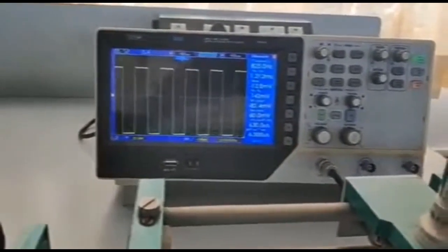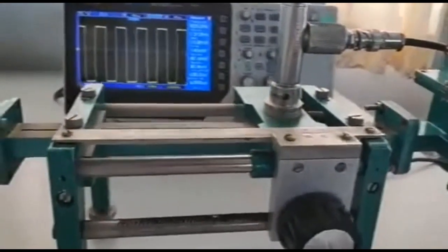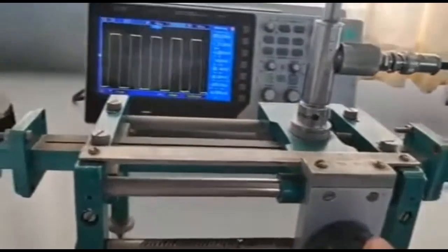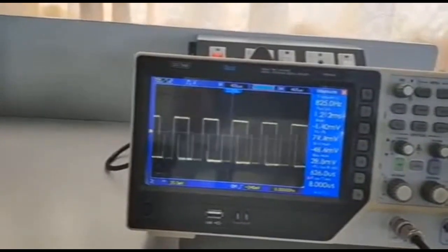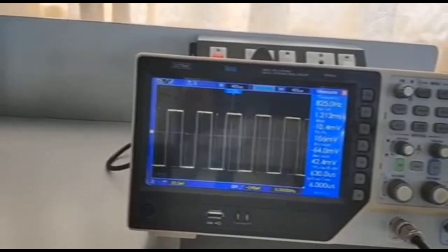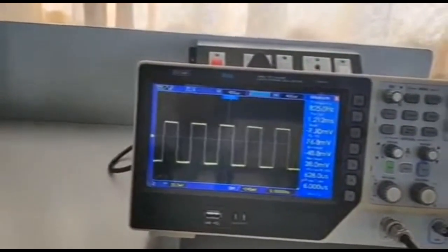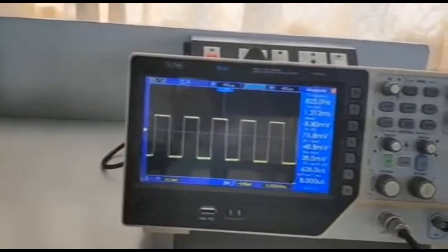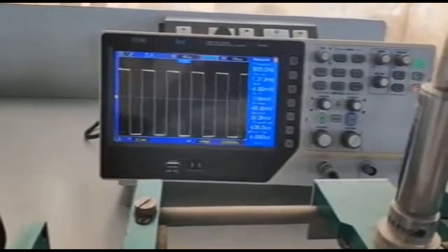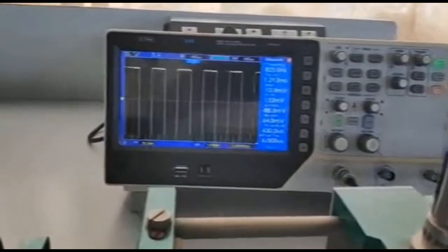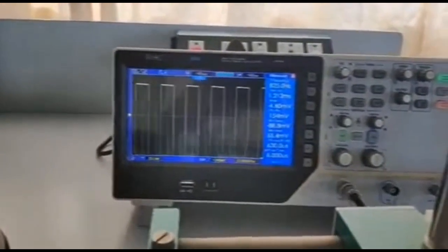In order to find the VSWR, I need to measure the minimum voltage and the maximum voltage. So to measure that, rotate this SLC knob and observe the voltage. So the voltage is getting reduced. So this is the minimum voltage, 76.8 millivolt. Similarly, continue this rotation in order to obtain the maximum voltage. Okay, so I got 153, 155. So that is the Vmax.